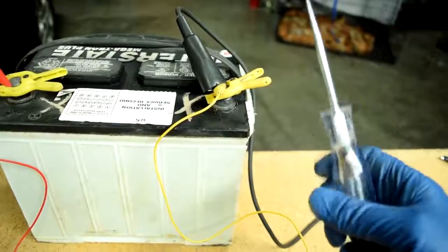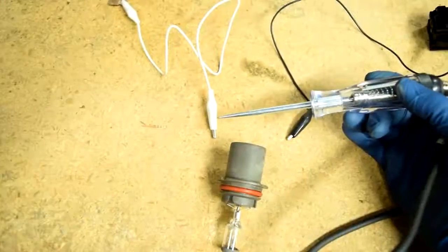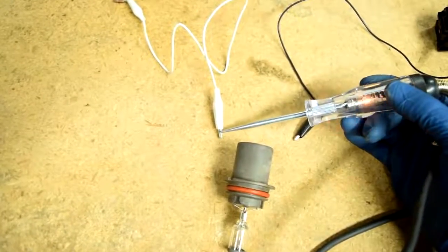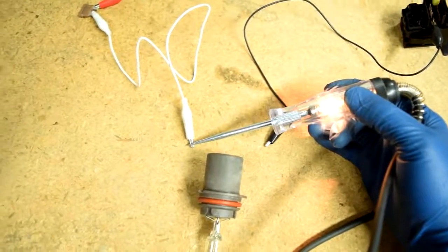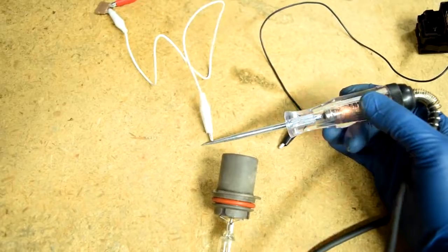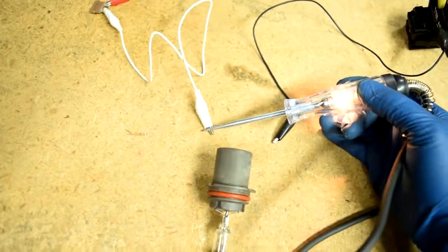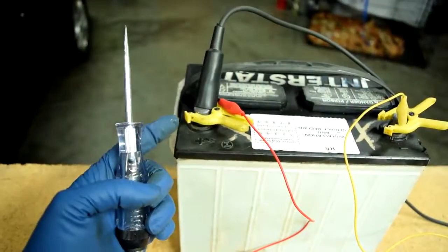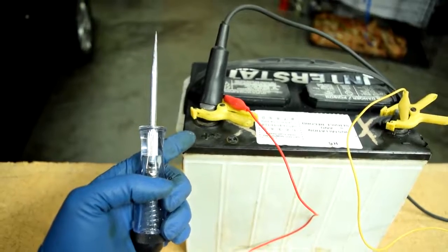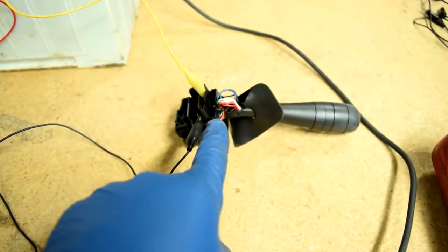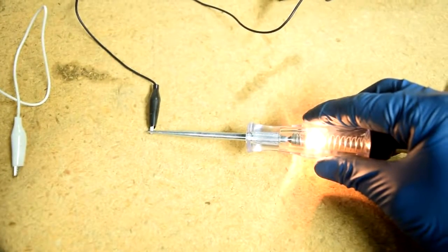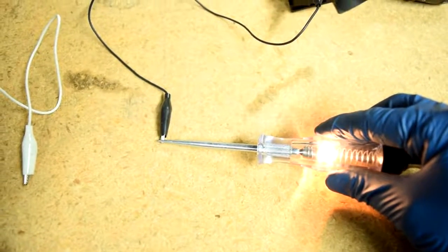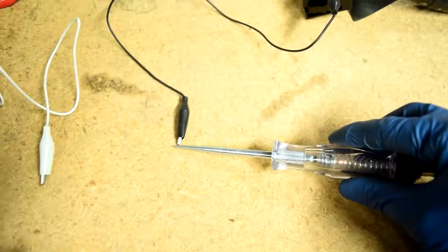First, grab your test light and ground it, and then probe the terminal on the connector that's supposed to supply power. And if it lights up, that means that you not only have continuity from the battery to this terminal, but also current can flow through it. And next you'll switch to the other side. So you attach your test light to the positive terminal. Next, with your headlight switch turned on, probe the terminal that's supposed to supply ground. And if it lights up, again you have confirmation for both continuity and current flow.